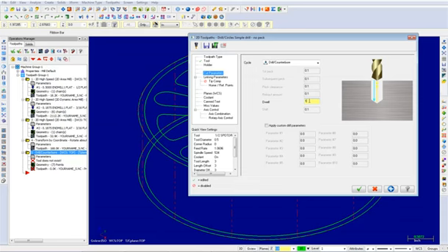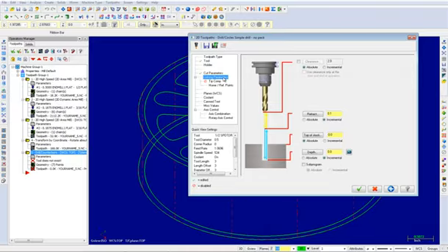Once the values have been changed, select the linking parameters. Ensure that clearance is enabled and set a value equal to 1. For the top of stock, set this to incremental and 0. Next, set the depth to incremental and select the calculator icon as shown.